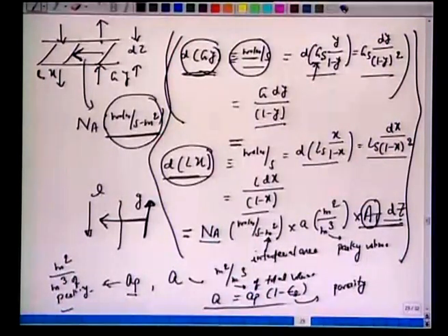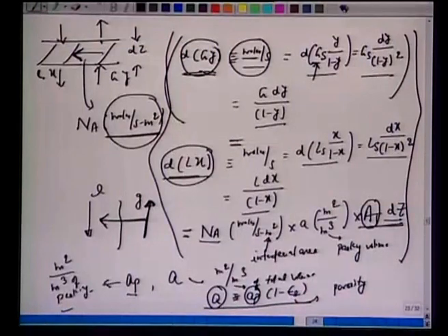So, let us be careful in terms of using certain nomenclatures, whether it is A or AP or what is supplied by these manufacturers. All right. So, we have made this species balance between the two phases, gas phase and the liquid phase. Where is the balance? Balance comes through this flux Na, through this interfacial area A, meter square per cubic meter of the packed volume.